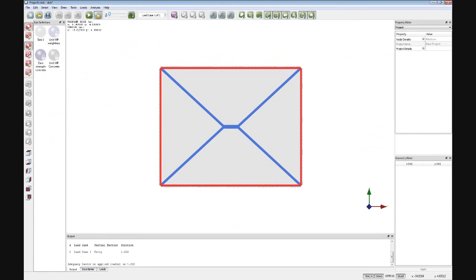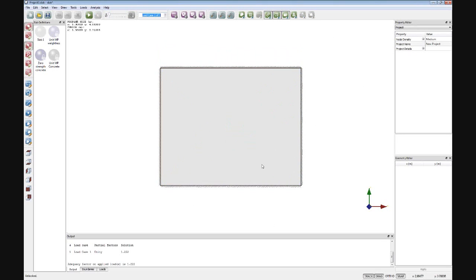So we've done that. We've got an adequacy factor of 1.22. We've got this quite simple envelope shaped failure mechanism. One of the beauties of the software is that you can very quickly make changes to it. As I alluded to earlier, the wizard is seen as a quick entry into having a model that you can then play with later and adapt to your needs. So if I just unlock this, go back to the basic rectangle, one of the things that we might want to do is use an orthotropic slab definition rather than an isotropic one like we've been using originally.